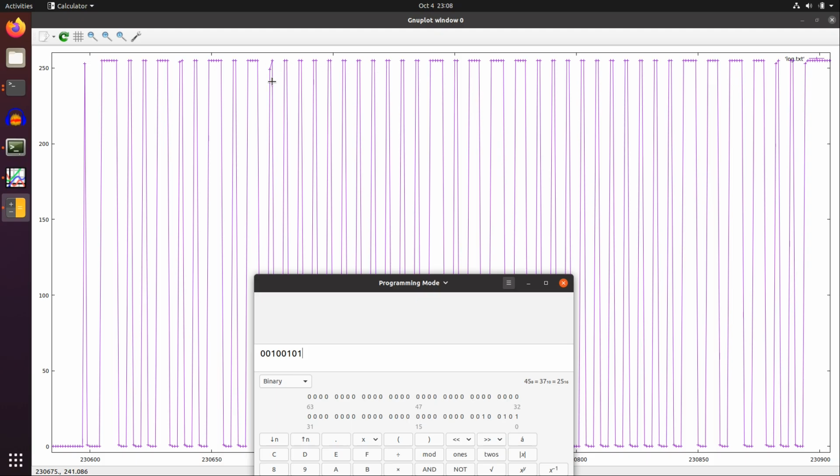Then the temperature follows. So we have here 1, 2, 3, 4, 5, 6, 7, 8. Up to here is the humidity. Then the temperature is 0, 0, 0, so let me type it in: 0, 0, 0, 1, 0, 1, 1, 1. This should be 8 bits. And we have 23 degrees here. So this is the temperature.